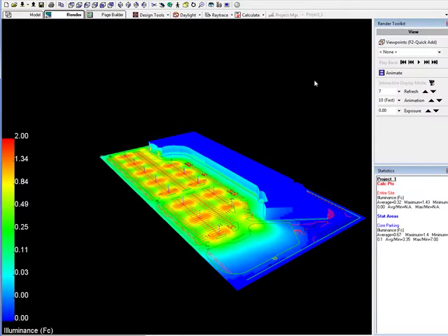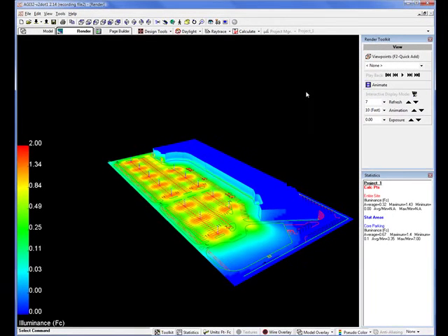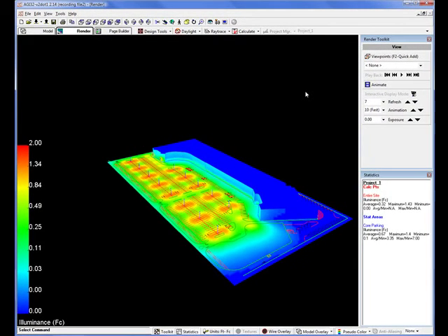Exit the dialog and now have a look at the building facade. We see an even 0.2 foot candles of vertical illuminance on the lower portion of the front facade. This is the same as our design minimum in the parking lot. Acceptable? You decide. We can export any rendered view to a JPEG or BMP format file for use elsewhere.